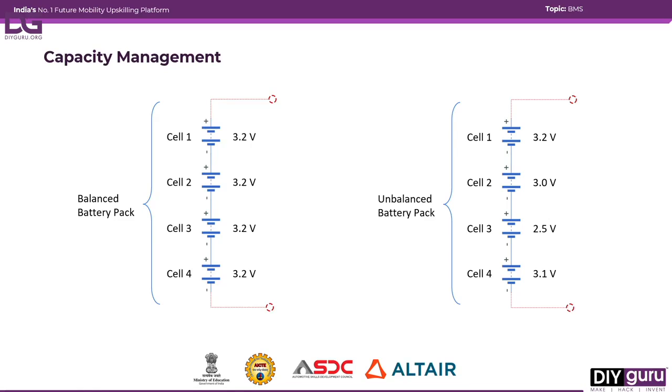This looks very small at an individual cell level, but when you are looking at a very big battery pack of an EV, where we are looking at more than 1000 cells, this 0.7 volt will make about 70 volts of difference, which is very significant when we compare the operating range of the battery, right? It's not like 1 to 4.2, it's 2.7 or 2.6 to 4.2. So already we are working at a very small range, and if you take out such a large portion, then the capacity will reduce drastically.